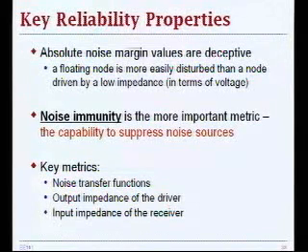We will see how this applies later on in the study of different logic families. You will have, for example, dynamic nodes, which have floating nodes, and we will also study static circuits, which have all the nodes connected to low impedance ground or VDD at all times. So noise immunity, in addition to the noise margin, is a very important metric. It tells you about the capability of your circuit to suppress noise sources.